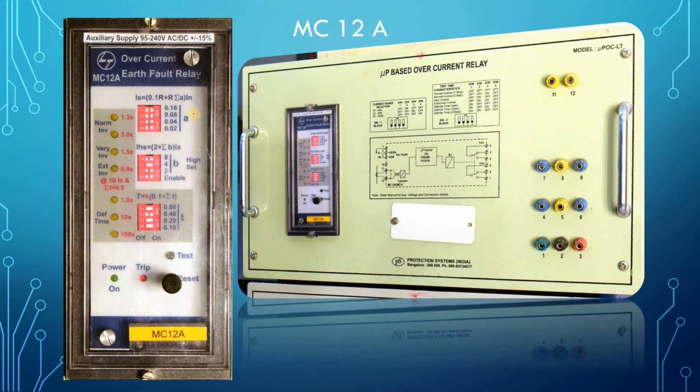As I told in the electromechanical case, a relay can be used to operate as an earth fault relay if it can detect a small amount of current as a fault current. That means if the relay is more sensitive, then only it can be used for the earth fault relay. As we know, the IS is 0.1, so this relay can be used for the earth fault relay.